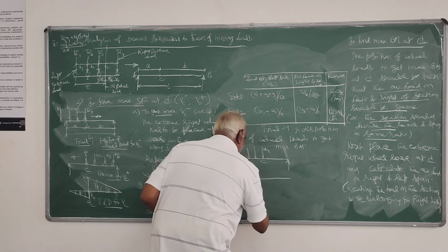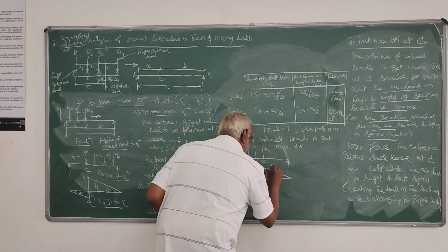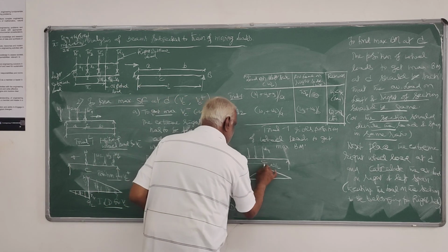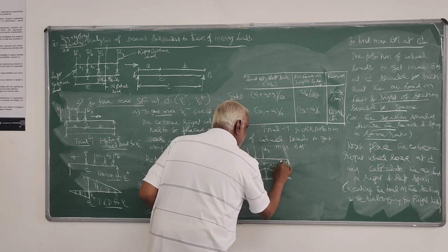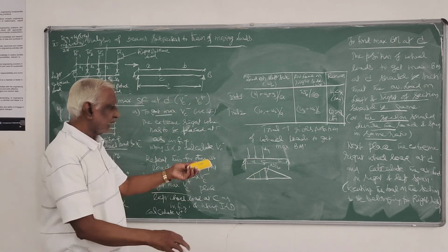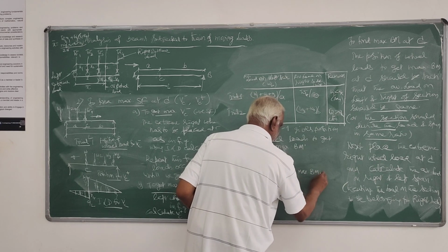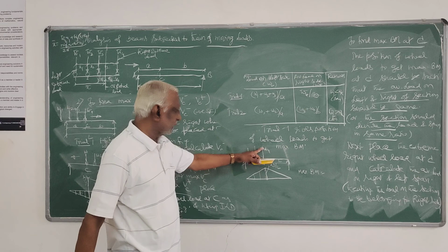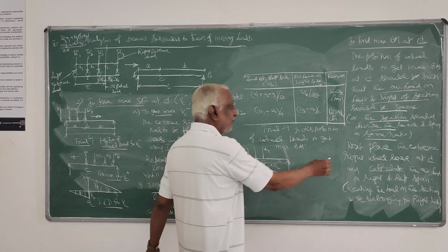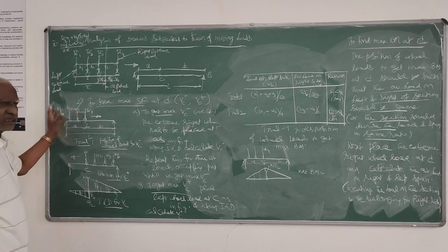Then you use ILD. So this is the maximum ordinate, which is nothing but AB by N, where this is A, this is B. You get the other ordinates, calculate the maximum bending moment. That is W4 into this, that value you calculate. This is when you place the extreme load and do the calculation.